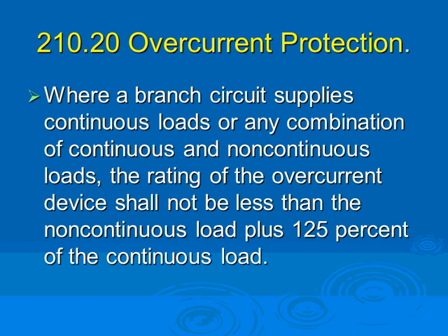This is just telling you about the continuous load. If you are to size the branch circuit supplying continuous load, look what you have to do. The overcurrent protection device shall not be less than the non-continuous load plus 125% of the continuous load.